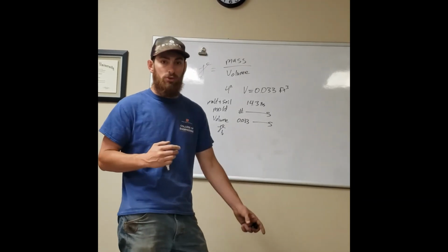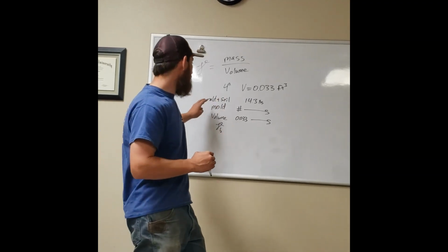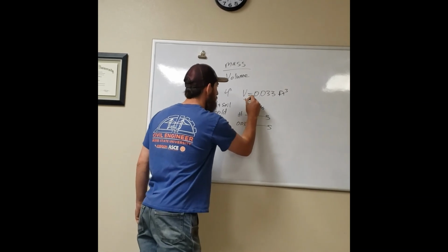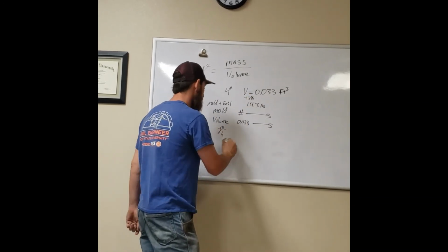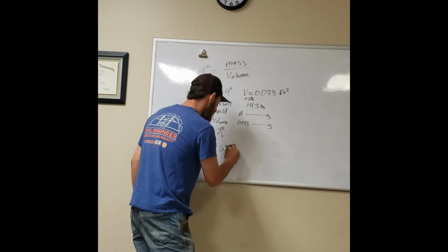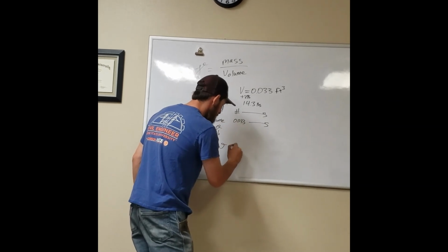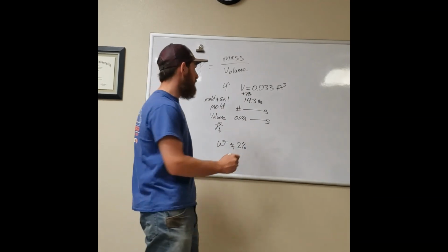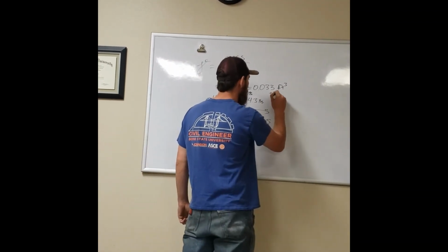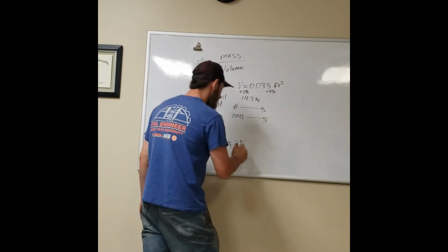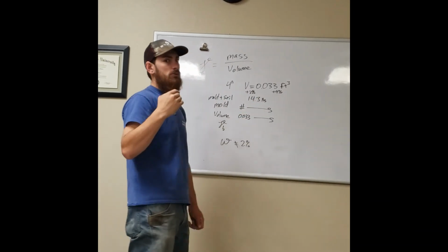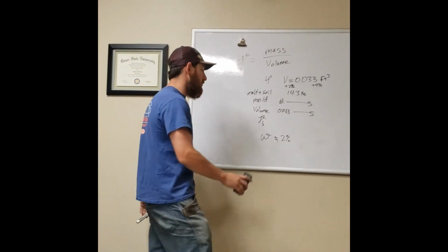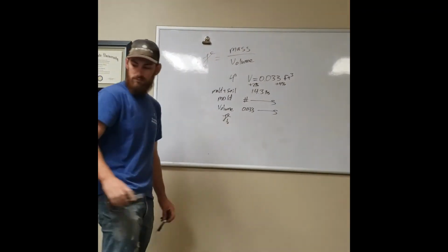So if I say plus 2% moisture that I'm adding, my moisture content isn't necessarily 2%. It's just 2% from where it was. So if I add 4% to the whole thing, again, it's not equal to 4%. I just added 4% from where I started. That number is arbitrary because we're going to need to do the actual unit weight calculations anyway.